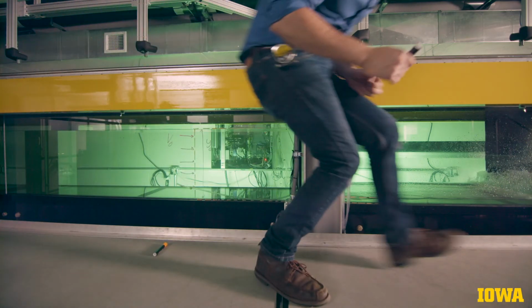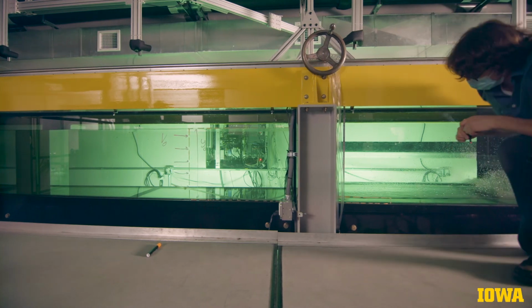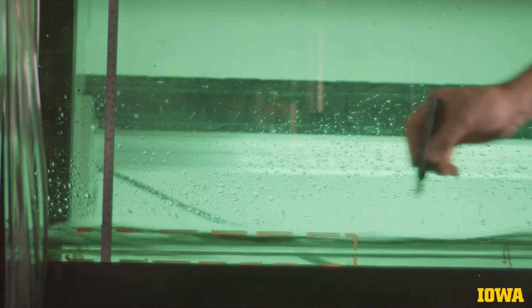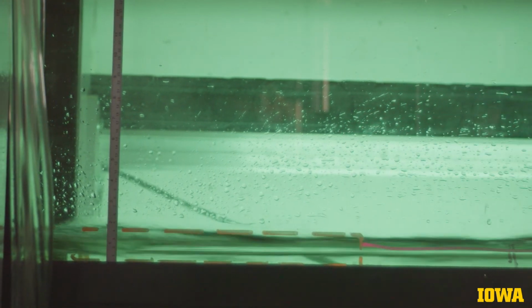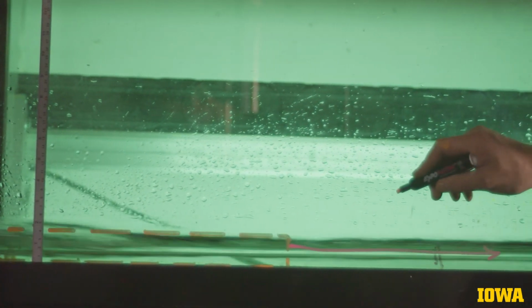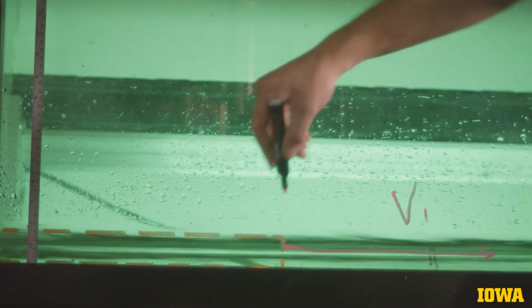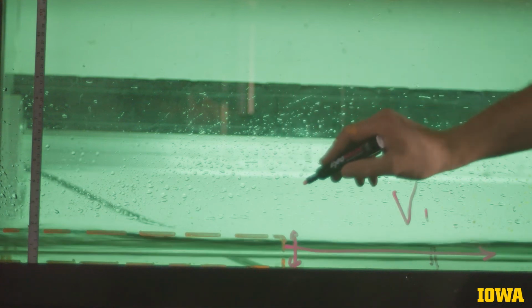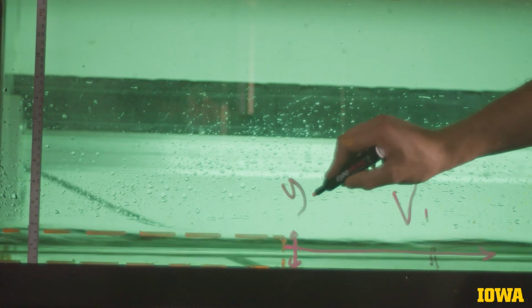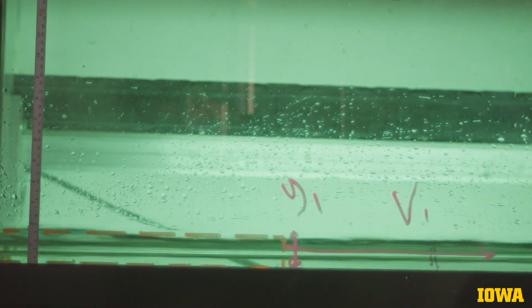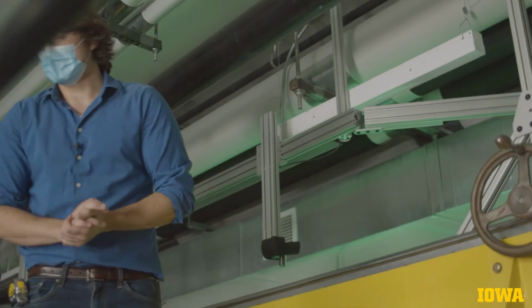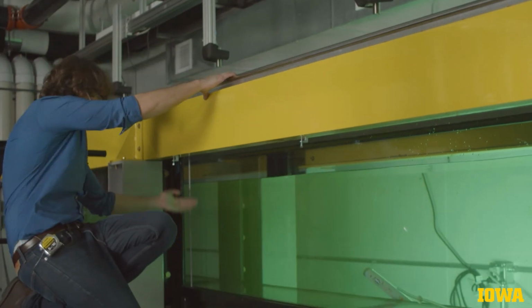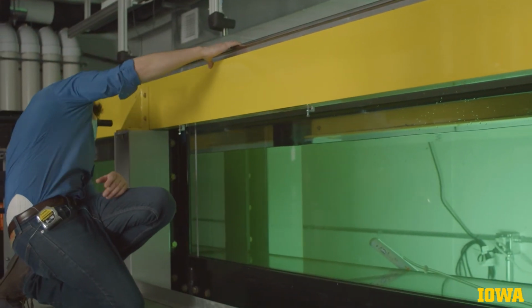Downstream from the gate, we have a much smaller control surface through which the flow exits at a much higher velocity, which we're calling V1, through a much smaller surface with a height of Y1. Just as before, we'll obtain the depth upstream using the linear rule adhered to the side of the flume, which